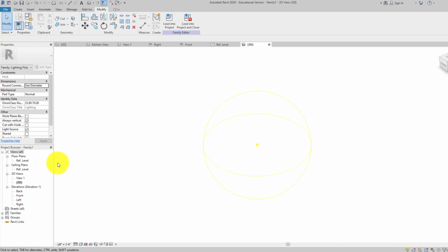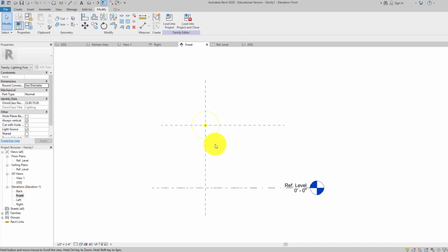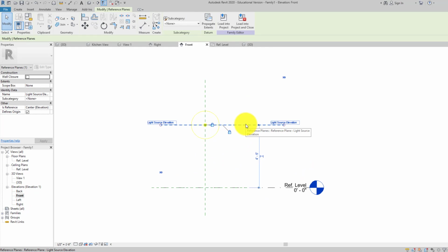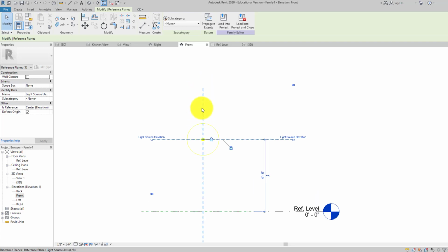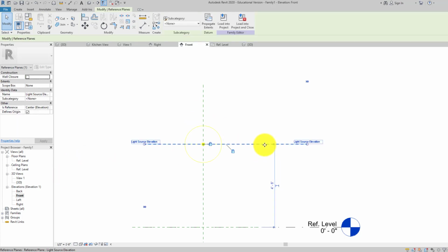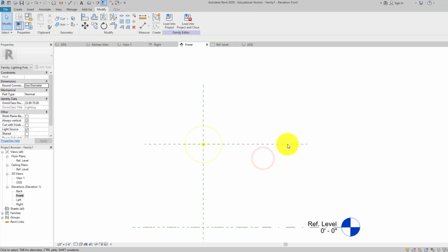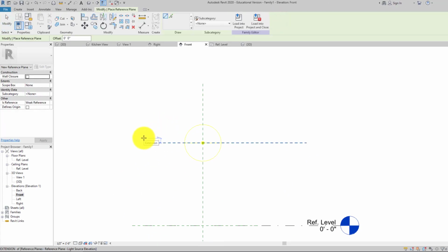Basically what I'm going to do is work from the side view, or one of the views, and you can see it actually has it off the ground, which is kind of nice. Which would mean we got 3 feet 6 for a regular drop down here. So let's go ahead and work with that. So what plane is this? Actually let's work from this side and make our own new plane. So create reference plane, and I'm just going to throw it up 3 inches above this one.